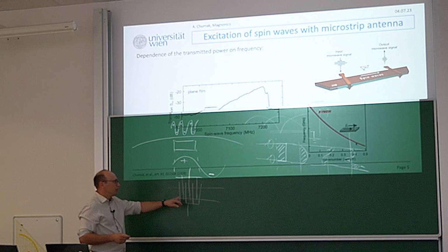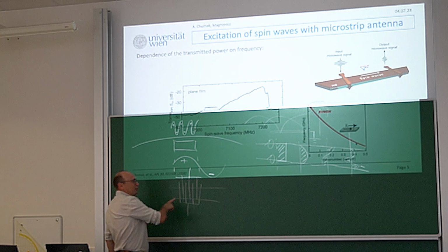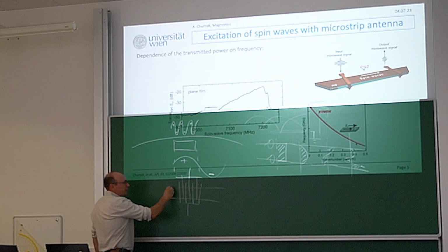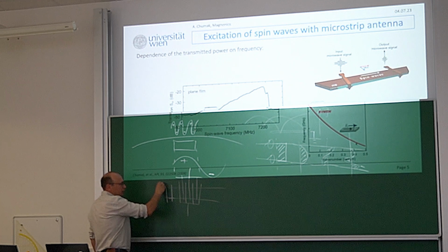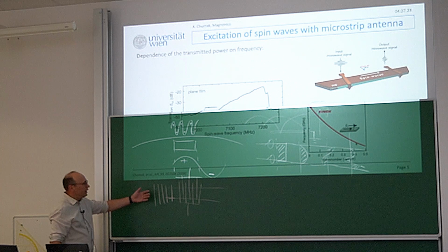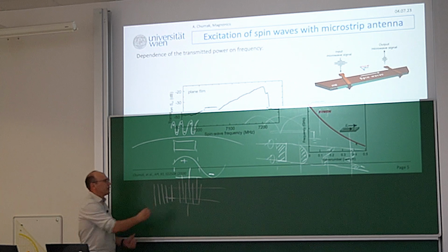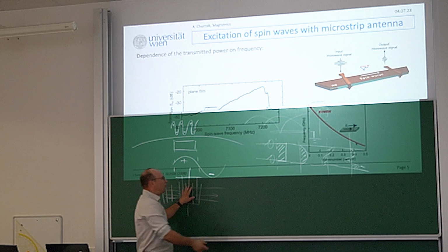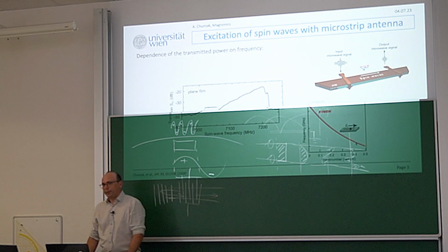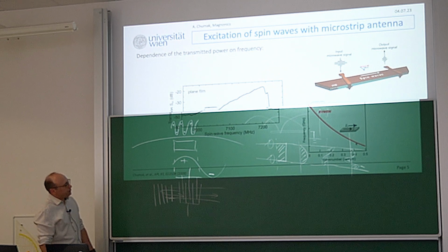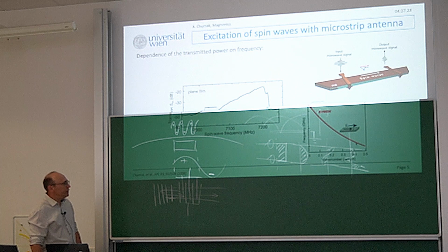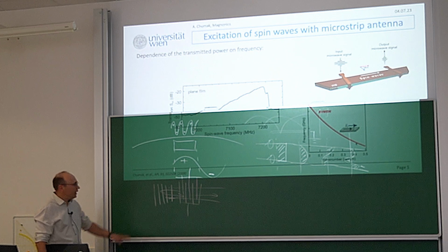this antenna usually excites with an efficiency of minus 3 dB because 50% goes there and 50% goes here. But what they did in order to avoid it, they placed Bragg mirrors here. From the same metal, they just put such an array of stripes, and then everything that is excited in this direction is reflected and goes on in phase. Therefore, they have a transmission from one input to output of less than 1 dB. They're really cool. And in our case, this also would be the way to go. The only point is, you can still do a magnonic crystal.